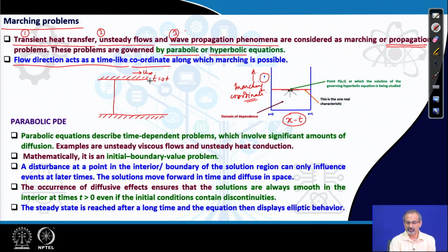Because it is a viscous flow, the flow cannot slip on the upper surface, and therefore, along with the wall, all the fluid particles adjacent to that wall also start moving with velocity u infinity. And after a while, you will find that momentum will percolate from the moving fluid to lower layers like this. And finally, after a long time, the velocity distribution may look like this.